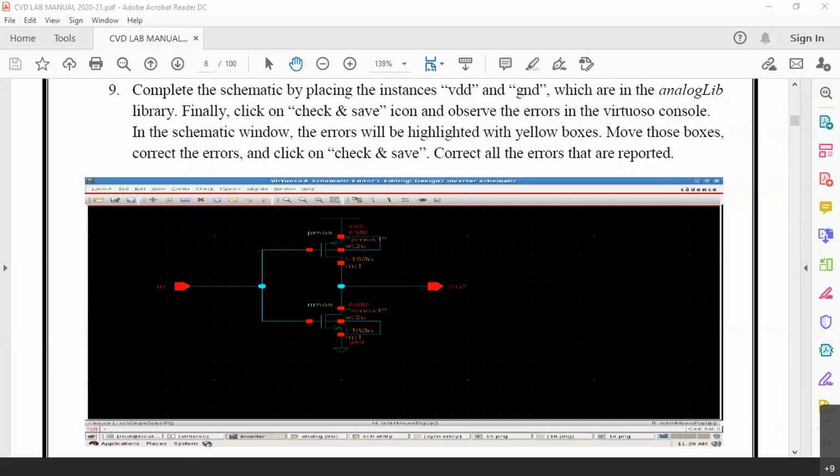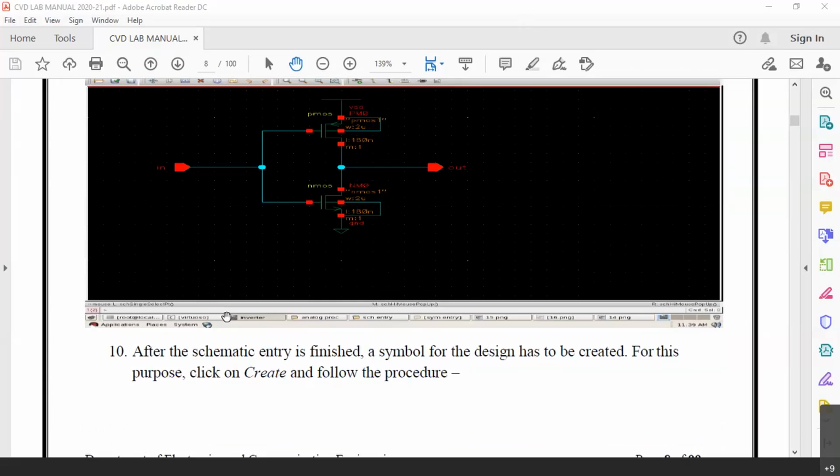In Cadence, when we construct all these symbols, it is actually possible that we can keep on moving from upper level to lower level or lower level to upper level. That means once you simply double-click on the multiplier symbol and you give a command there, it will go down to the adders level. If you choose the adder and go down, you will get into the gate level. Again, you choose the gate and go down, you will come to the MOSFET level. So, as I told you, this is an industry standard tool and all such possibilities are available in the tool. Now, let me proceed further for the construction of the symbols.